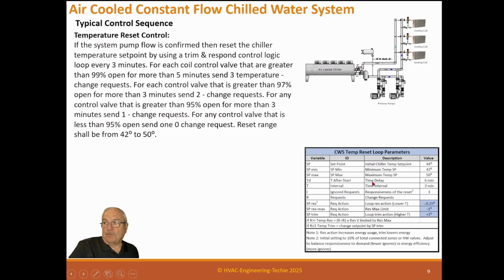The temperature different delay time, so when it first starts up, it's going to do a 6-minute delay. And that's just to let things get settled out in the building before we start resetting something. If you only waited 3 minutes, you might do something that you didn't need to. Now you have to reverse it. So the 6 minutes is to give things time to settle out.